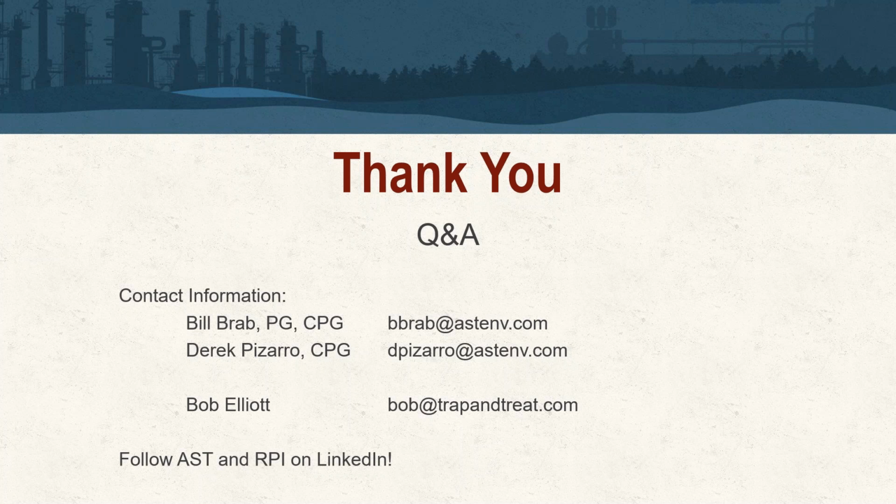So there is a lot of upfront characterization, design, and assessment. But then when you get into the field, it also becomes a little bit of an art as well. It comes from experience. It's reading output pressures in the freshwater test. It's reading the system and output pressures during injection. Sometimes it's even visual. Bill had a slide up from a site, I believe it was in Connecticut.